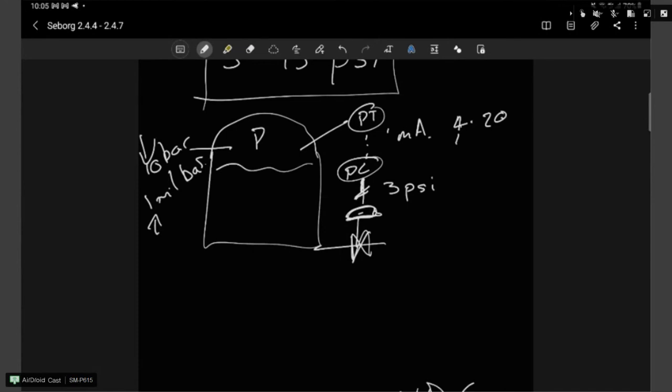correct, because of the force exerted on that. Remember, it's not necessarily just the upstream process, but it's also the downstream pressure that determines that. Because if you have an air to close valve, and there's a chance that your downstream pressure can increase, then it needs to have force exerted on it such that it overcomes that back pressure, so the valve doesn't leak.